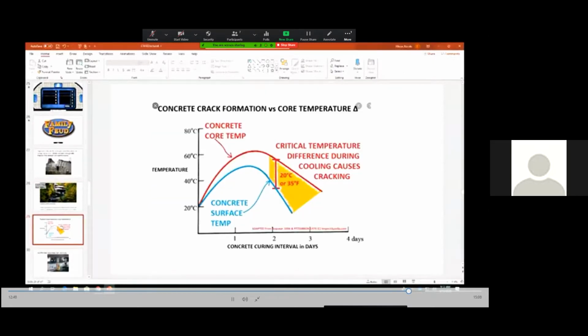So the other thing that is important, we talked about those environmental factors. Is it going to be placed when it's hot or when it's cold? And then after it's in place, is it going to be subject to cold and hot? So the civil engineering building is a concrete structure, and most of it's enclosed, so it's firmly controlled. Whereas if you had a garage that's outside or a street or a walk, it's going to be exposed to those climate changes like we have in Colorado, right, where it's like 90 degrees one day and the next day it's snowing.